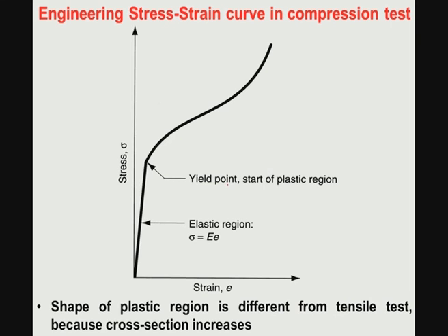This is the compression stress strain response in case of metals. The fundamental similarity between the tension and compression is that in both cases it started with a linear response. In case of compression, the metal will undergo non-linear response, but will keep on increasing. So, in case of the tensile response, metals will behave this kind of way, but in compression this response is quite different.